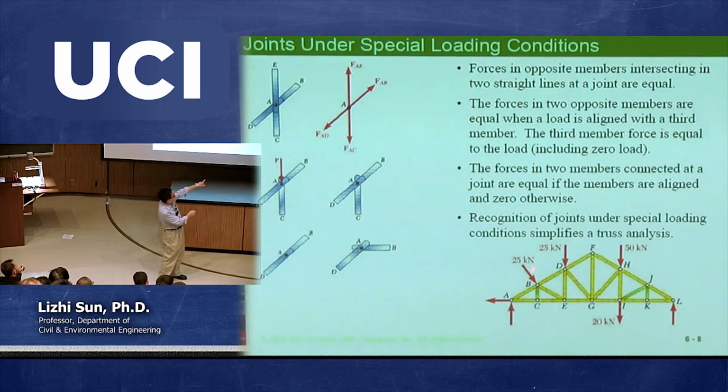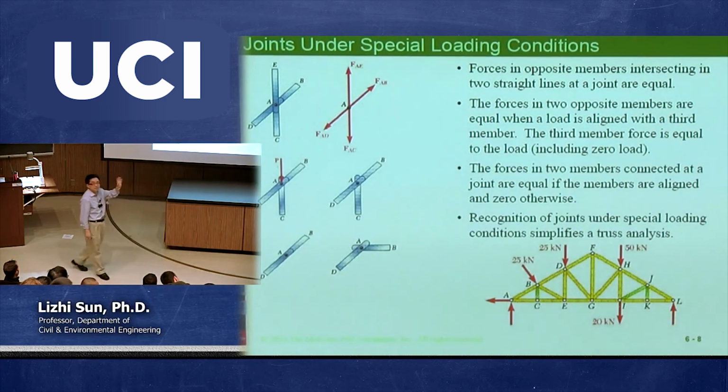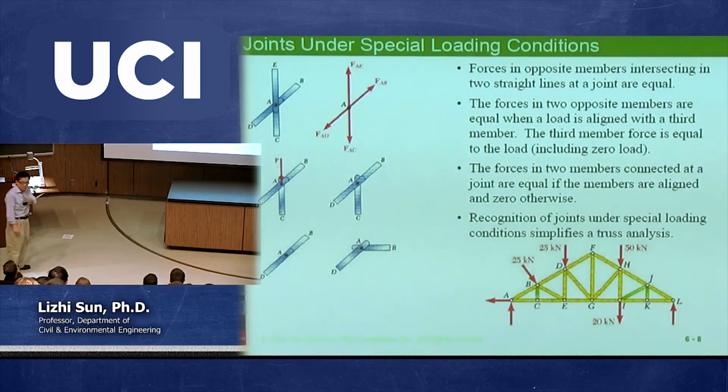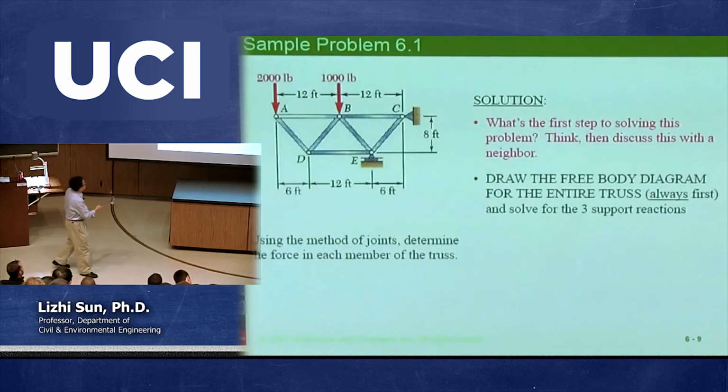But let's say, just in case all the force is in the y direction, then the question people would ask you is why you are designing a pin at joint A instead of putting another roller. Because if there's no horizontal force, this one is guaranteed to be zero, right? But only for that case. But sometimes when you have a small disturbance, a small wind, if you do not have any resistance in the x direction, then this structure will fly. Okay? So that's why you have to prevent such unpredictable cases. Okay? So thank you. You're right. Backup. Okay, so this is the method.